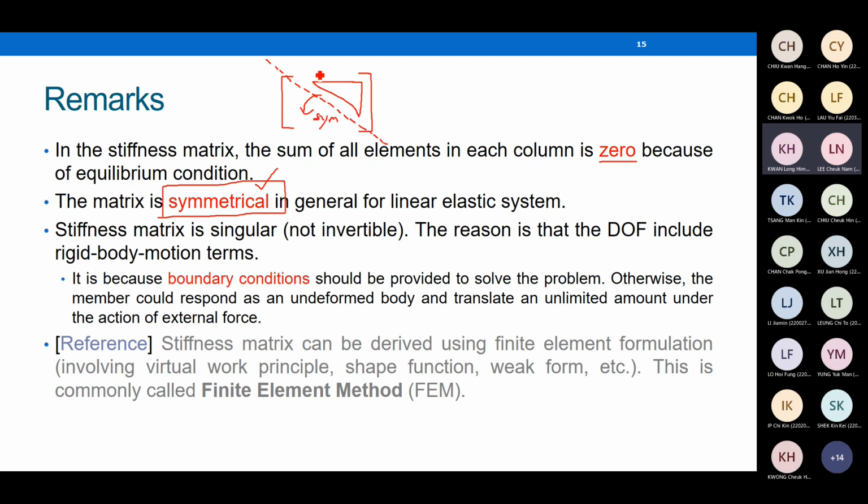Okay, you can flip one side to the other side to construct the whole matrix, which means it is symmetrical. The stiffness matrix should be symmetrical. Otherwise, it means you did something wrong in your calculations. This also helps you to simplify your calculation, right? Because that means you just need to know one part of it, not the whole thing. If you know the top corner, then you can reproduce the bottom corner immediately. You just need to know one half.